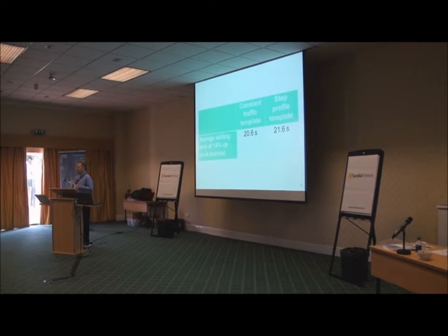And if I then compare my constant profile with my step, at the point at the 14%, which is what the handling capacity of the system was, then you can see again it lines up quite well. It would line up even better if my step was longer. Yeah, I've got a 5-minute step, so it doesn't line up that well. But if I had a longer step, the whole thing would stabilise. At the moment, I've got a transient thing because I've come from 5 minutes, going to the next 5 minutes, the next 5 minutes. It goes up and down a bit. But I can pretty well get a consistency between the two.